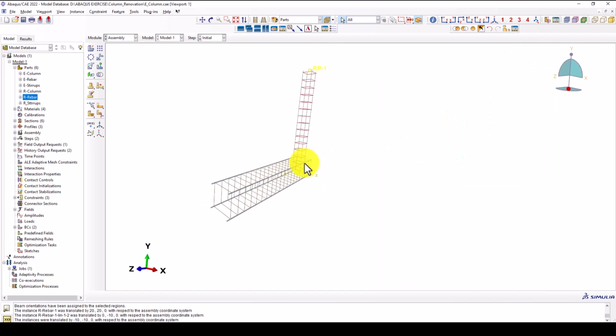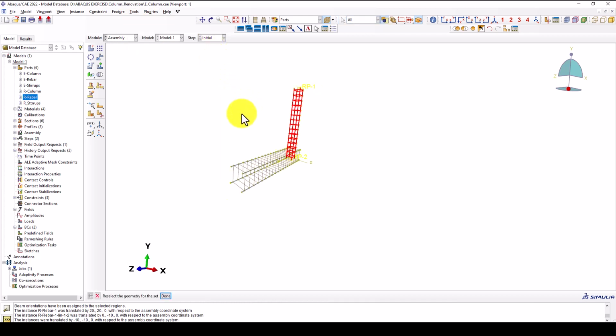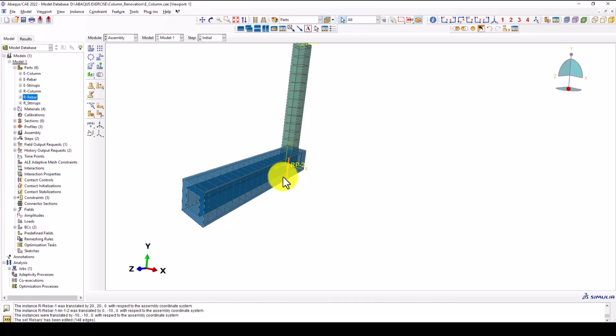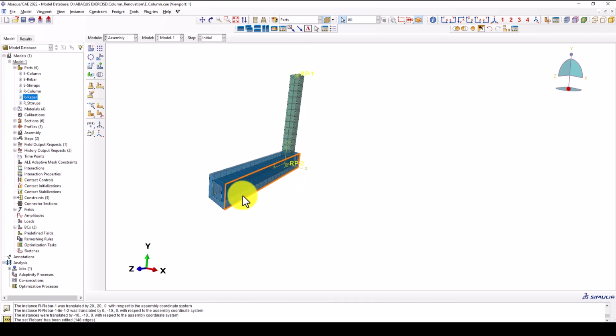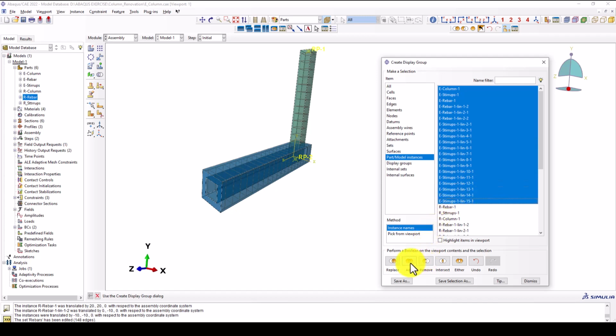So now this is the entire rebars, and previously we defined them here, called rebars. This time I want to select all rebars. So all rebar is selected, and I'm going to deselect these two. Next I'm going back to here, everything, and from the top to here I'm going to remove it.